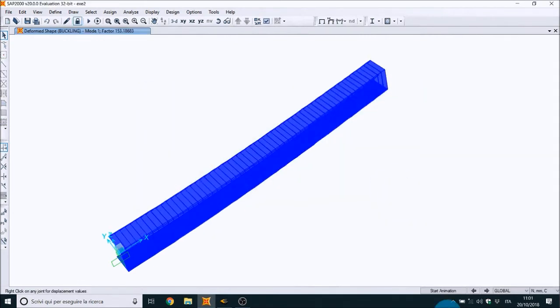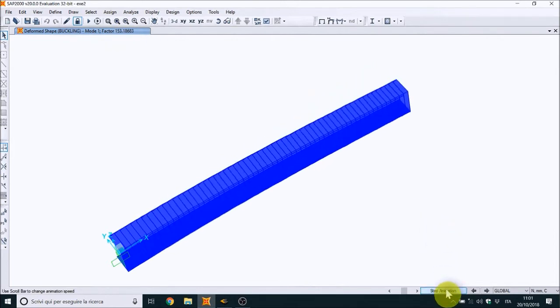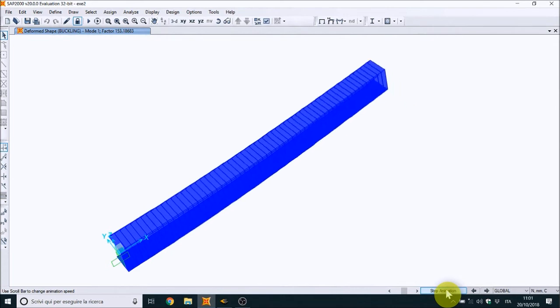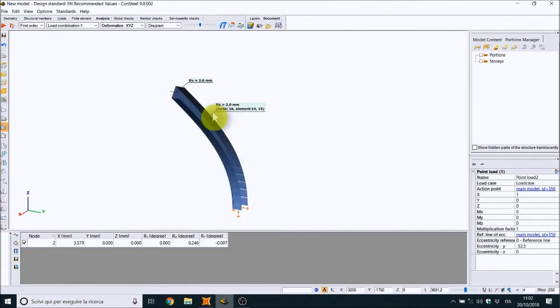You can see the behavior, the force buckling multiplier of our C cross section is a pure flexural one, but it is not correct because from the theory I have a flexural torsional buckling that is 3 times lower. I can use Consteel to calculate the right value.